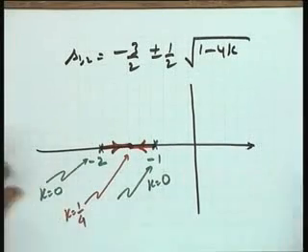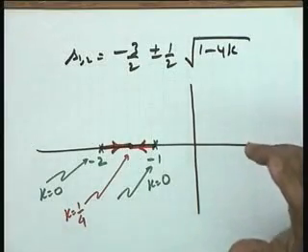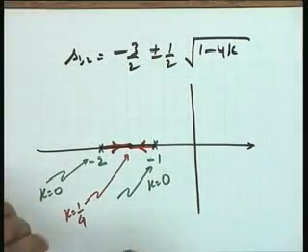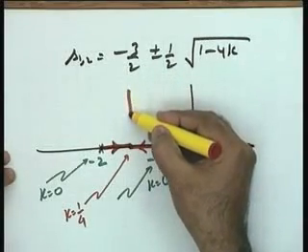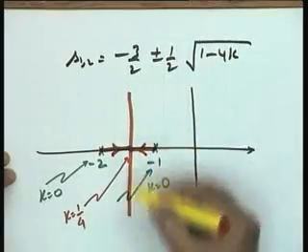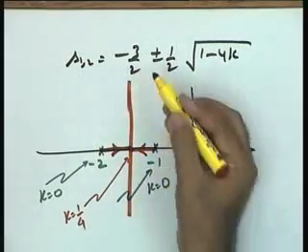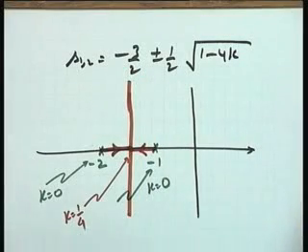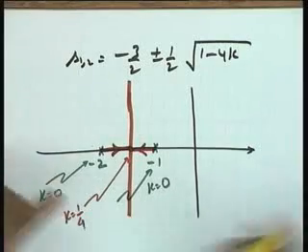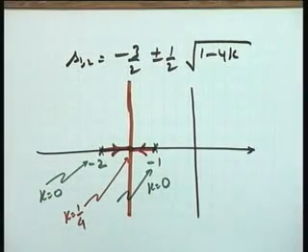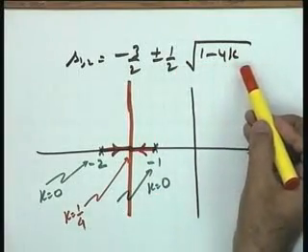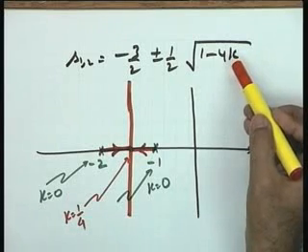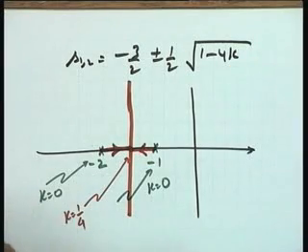Okay, help me please. If I increase K further, what will happen? What will happen to the roots if I increase K further? The roots become complex conjugate, and you can easily establish this, it being a quadratic. The roots always lie on this line because the real part is always minus 1.5. The roots have to lie on this vertical line, the real part being always minus 1.5. Only this part changes, and this part now becomes a complex part for K becoming greater than 1 by 4. So it means I can visualize it this way.